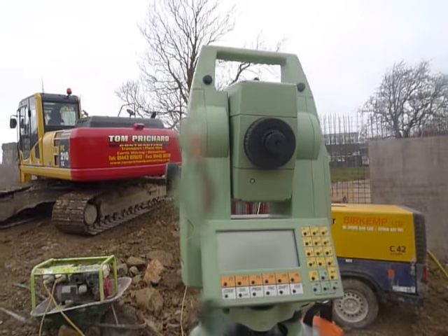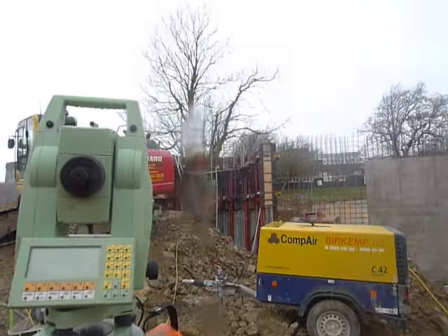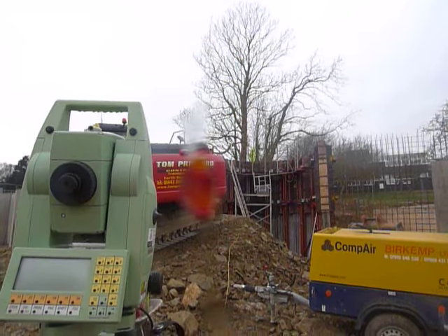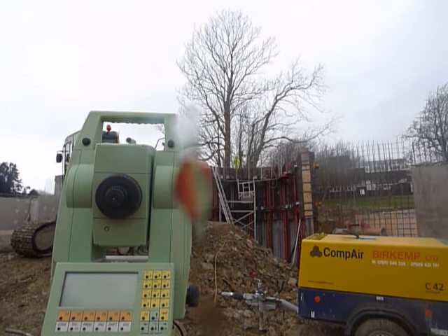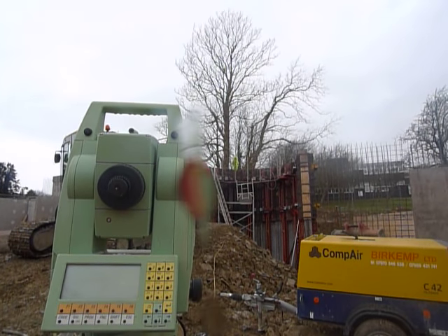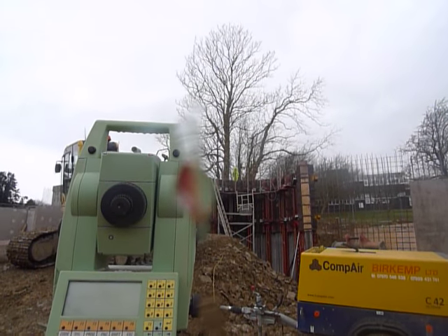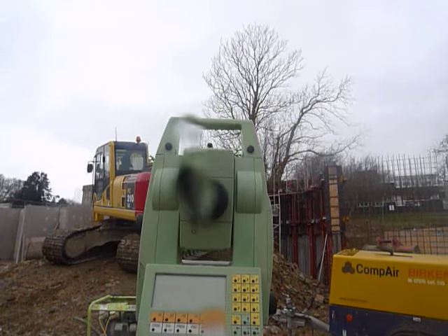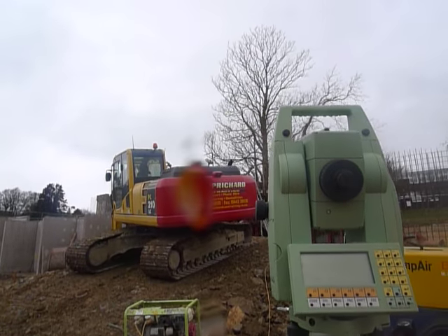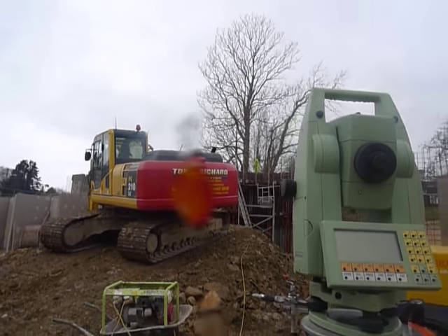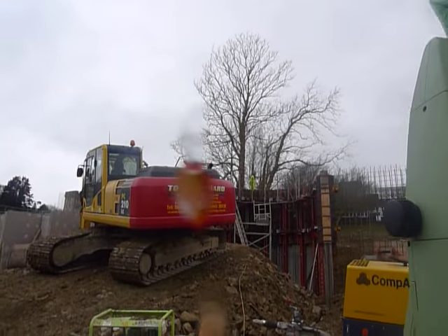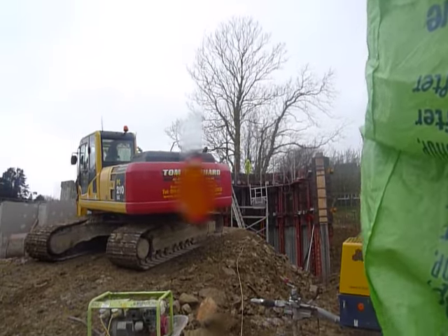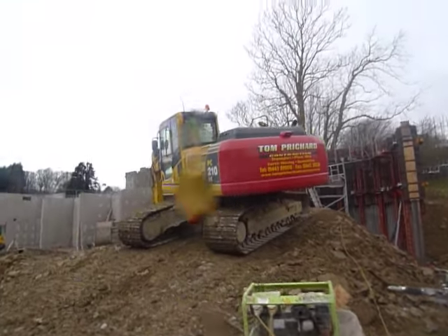So this is where my instrument is positioned, and from here I survey a cup with a laser hitting the shutter. I've got to be careful that I actually hit the ply and not something else. I'll get the coordinate of where my laser is hitting. So I take a series of readings from one side, and a series of readings from the other, because the laser has to hit the shutter in such a way that it's not an acute angle, ideally 90 degrees, but you can't get that. So, okay, let's go and have a look at the shutter.